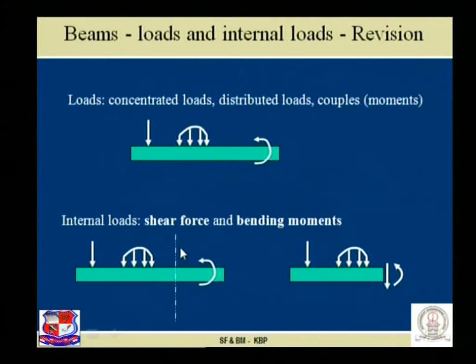Now, let us take a section over here. Because of this section, my beam has been divided into two parts, left part and right part. So just visualize, when I take an individual free body diagram of the left part, see these two quantities, this force and this moment. This force is referred to as shear force and this moment is referred to as bending moment, and our intention in this particular series is to find out the shear force and bending moment for a given beam, specifically the overhanging beam.